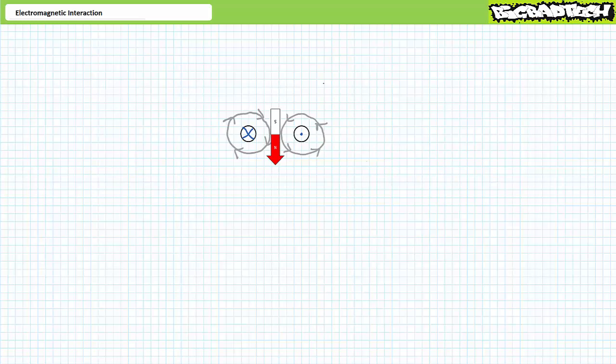Recall that magnetic lines of force outside a magnet leave a north pole and enter a south. Thus, a north pole is established at the bottom, and a south pole is established at the top. We've in effect turned this loop of wire into an electromagnet. Anytime current flows in this loop, we have a functional electromagnet. The advantage of electromagnets, in contrast to permanent magnets, is that the resultant magnetic field can be turned off. If current flow stops, the magnet stops, minus a tiny amount of residual magnetism.